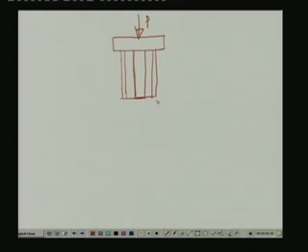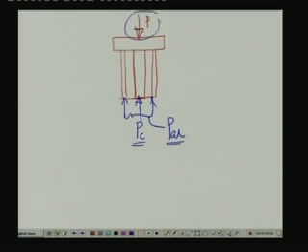So, in this free body diagram, if we now transfer the reactive forces acting on this, they are the force in the copper rod and the force in the sleeve, these two together. Let us call that the load in the aluminum. So, we have these two forces, P C and P aluminum, which are generated because of the externally applied load P.